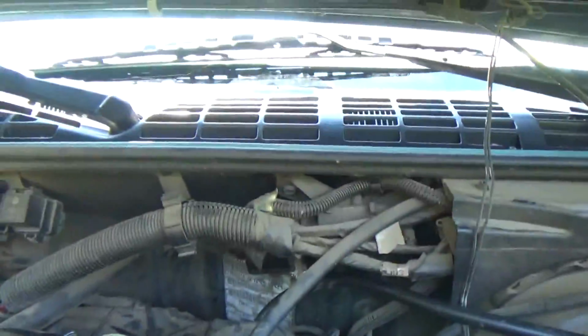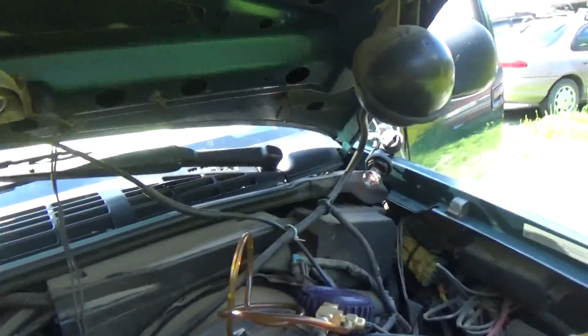So in this case, we'll just put in a new fuse, take it for a spin, and see if everything is good. Clear the codes out and see. Sometimes fuses do blow just because of heat cycles. You get a little crack in there that heats up, and eventually it's too hot and they blow because of age and wear and tear. Fuses can do that. I've seen that before.